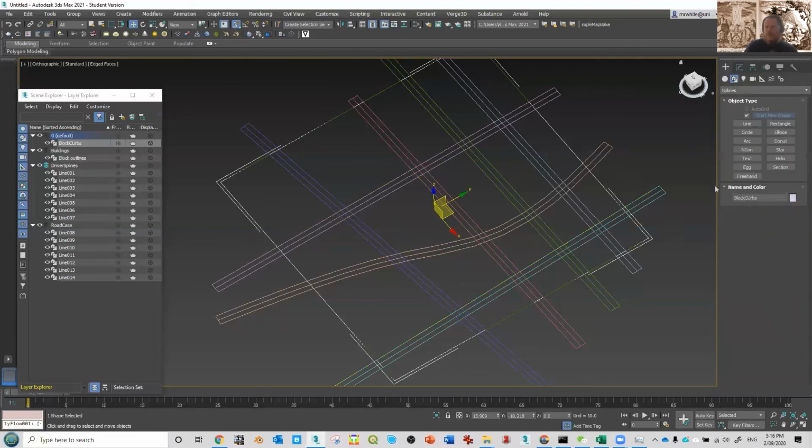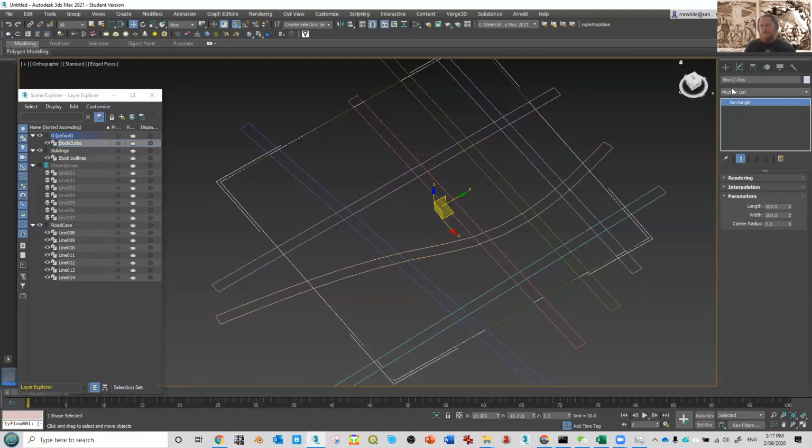Okay. So then I can do that same process again. And this is where I think probably if I did this another 5 times, I'd get the exact right order of duplication and stuff, and I probably wouldn't have to do this step. But what I'll do is I've got another rectangle, and I'm going to Boolean subtract these road casements again to create a kind of different shape.